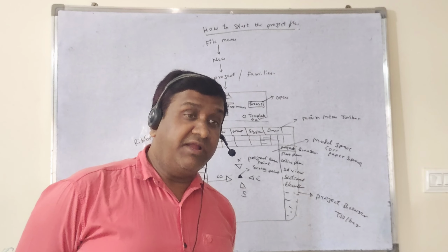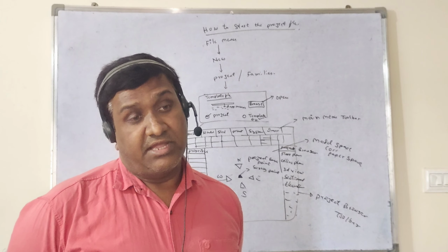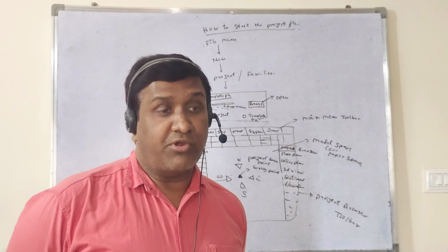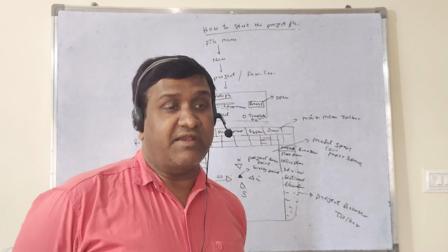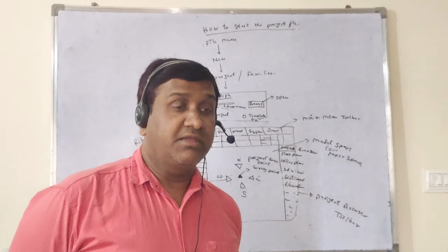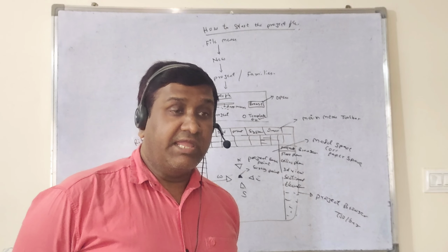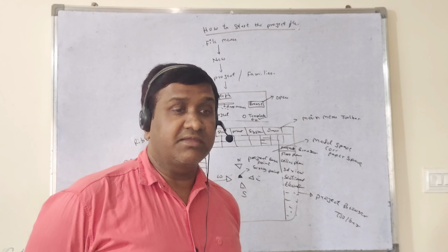So what is the base point, what is the survey point? The base point is our project base point, and the survey point is also our project survey point. You have to give these. This base point and survey point is nothing but your project location. Because right now you are in Kerala, Calicut, but your project is being constructed in Dubai.